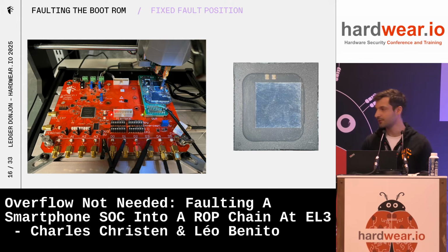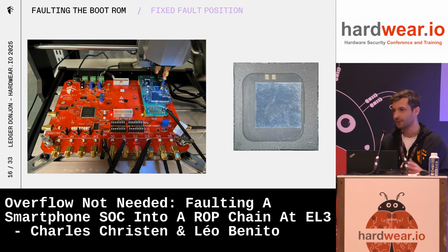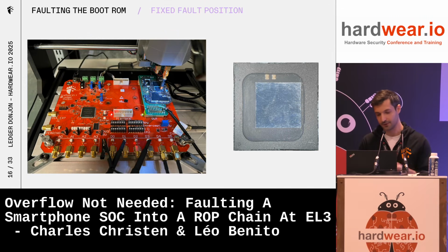Sometimes you can do a big search over the full space at once. Here we decided to first fix a position of the probe above the SOC, which gives us some perturbations, which is easy enough to do because, as I said, there are a lot of logs emitted over UART, so we can check if when we shoot with the silicon toaster, we get corrupted UART data back.